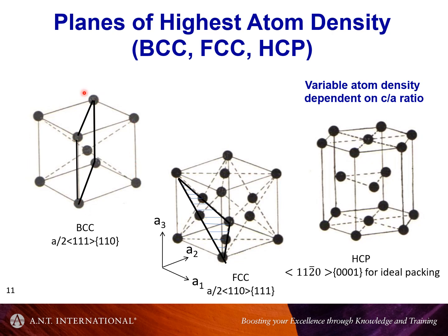That's good for diffusion if you want to diffuse through the BCC material, but it is not close packed, and that's because the inner orbitals of the elements that comprise BCC material, such as chrome or iron, in their raw state, they create this bonding. Even though it's a metallic bonding, they influence the way in which the atoms will sit in a low energy state.